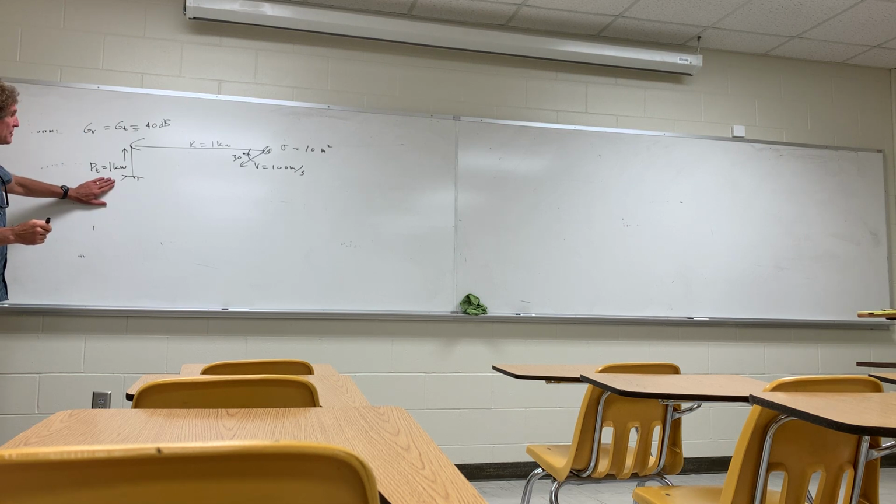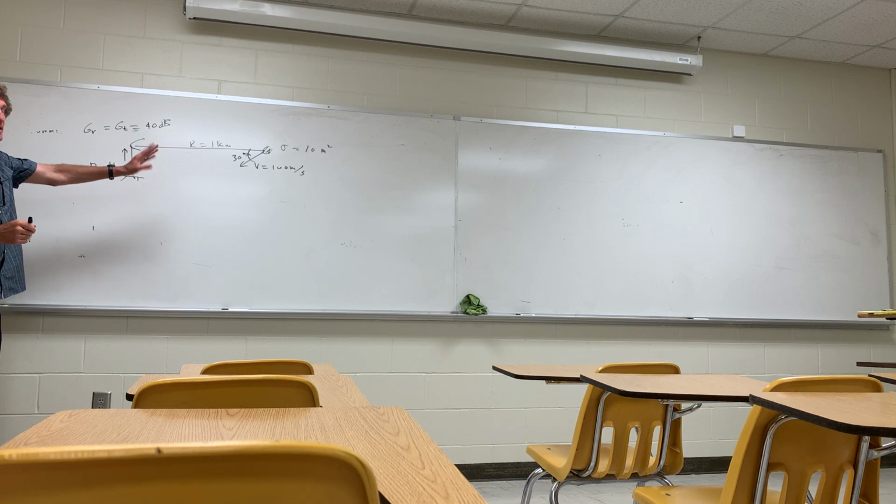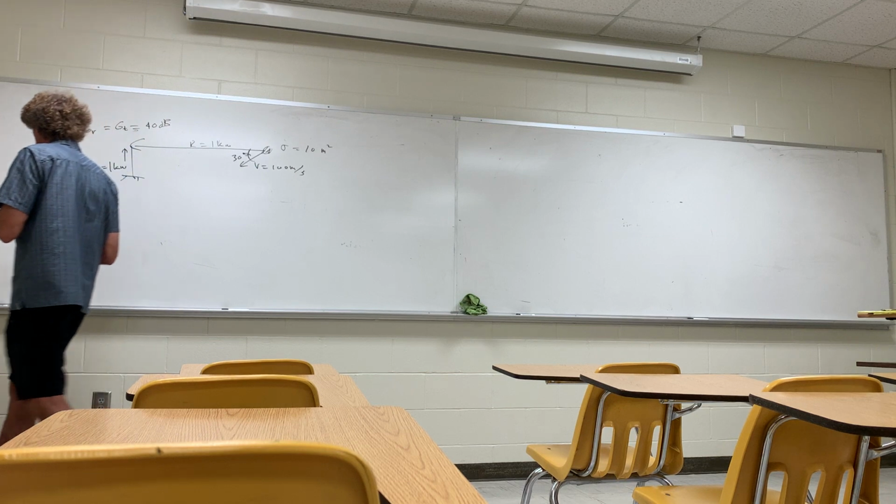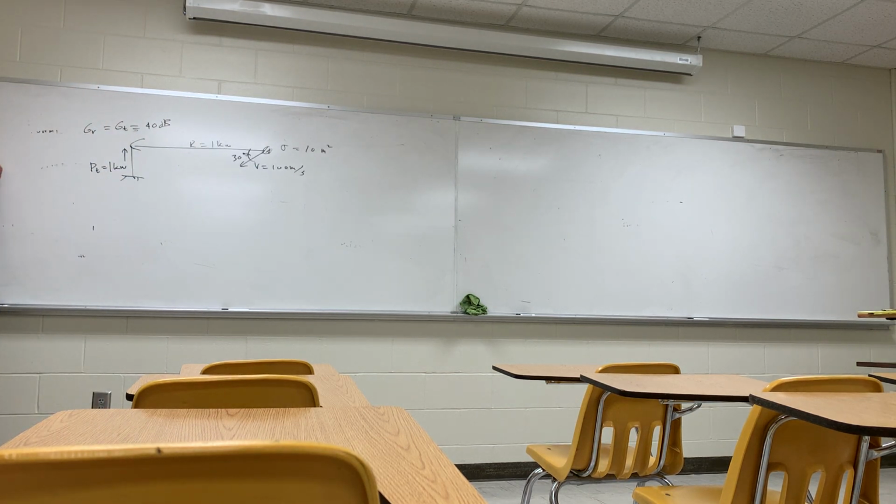So I've got 1 kW, got the range, 1 kilometer, I've got a 30 degree down angle, and now I want to find out something. And let me just do this. I'm going to say I have a noise figure of just 1. That way it'll get rid of that part of the equation. And now let me show you my pulse signature. This is the baseband pulse signature for the radar. It looks like this.